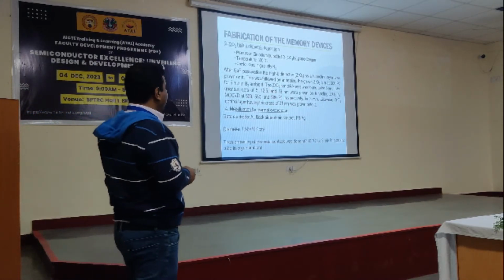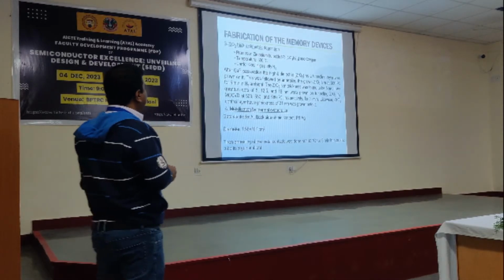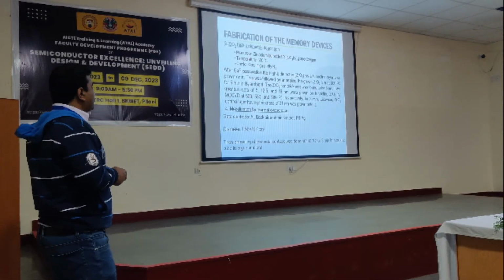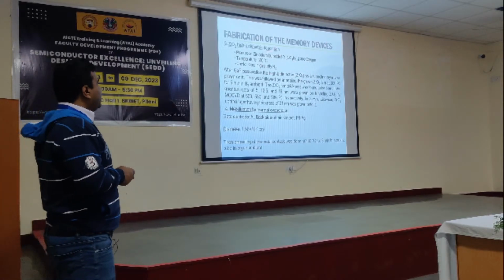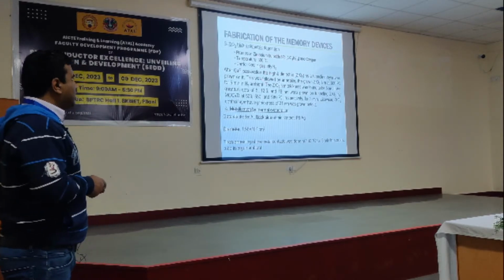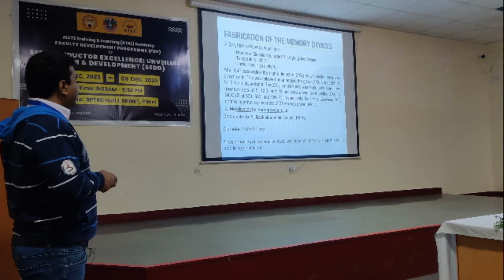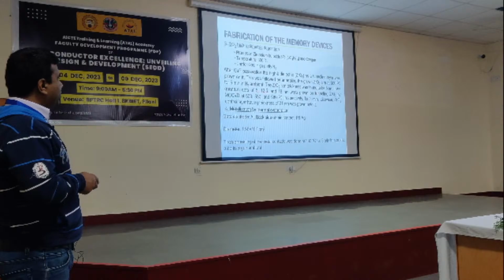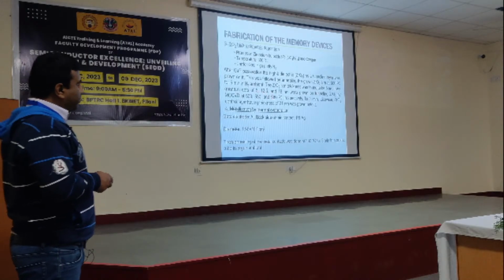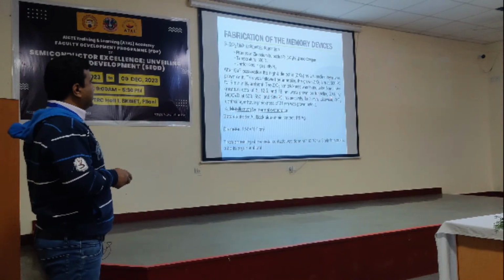indium arsenide quantum dots. You see, for ZrO2 the precursors are zirconium tertiary butoxide and oxygen, and these two materials react in the chamber and finally grow the ZrO2. After that, on your ZrO2, you see here, indium arsenide quantum dots of 5, 12.5 and 16 nanometer are grown on the tunneling ZrO2.